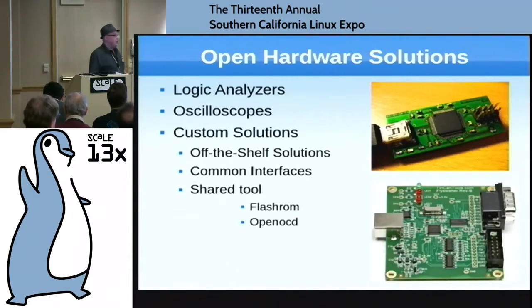Another one is shared tools. This really means that there are a lot of software packages that may have a very specific purpose. For instance, FlashROM is actually a tool that allows you to reprogram the SPI flash on a motherboard for your custom firmware. For instance, if you're dumping UEFI and you want to do coreboot or vice versa, you can actually use FlashROM to reprogram the firmware.